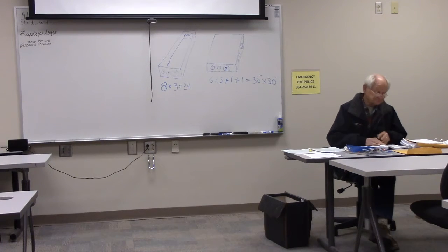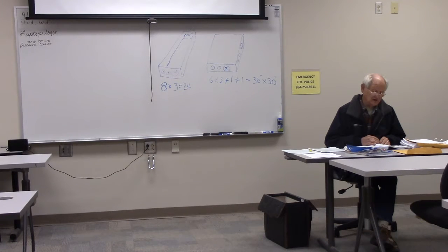A conductor under 12 inches long running through a box counts as a conductor equivalent of 2? Under 12 inches. Under 12. You even got me. Right. If there are 4 equipment grounding conductors in a box, you must deduct how many conductors from the total allowed? 1. Good. Factors to consider when installing boxes are covered in